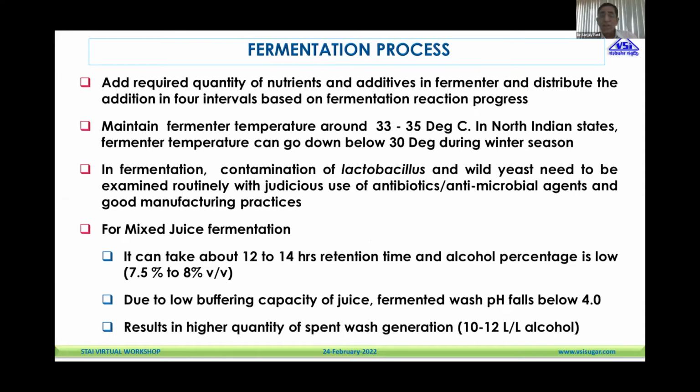We have seen in some of our visits to the North Indian distilleries that the fermentation temperatures were quite below 30 degrees, particularly during the winter season. So one has to take care to bring the temperature to 35 degrees centigrade. That will improve your fermentation rate.